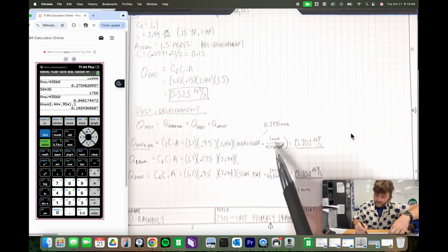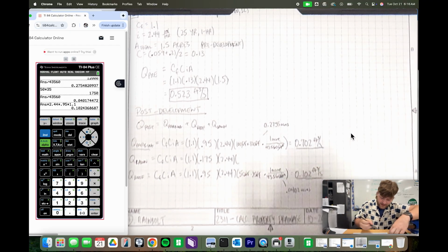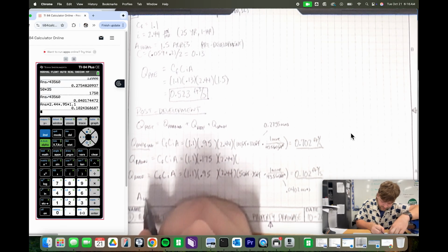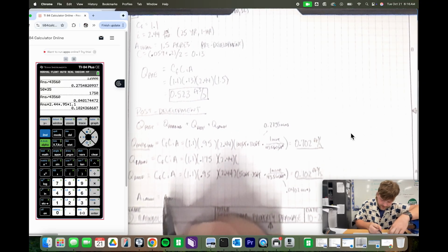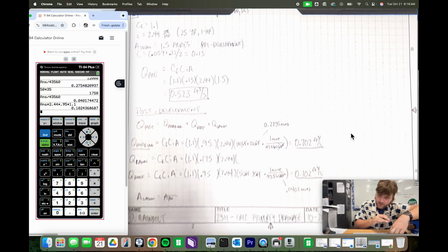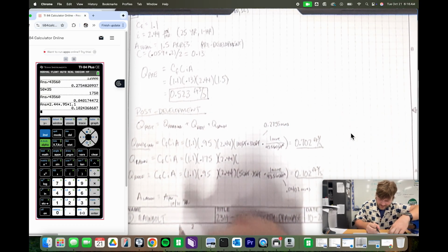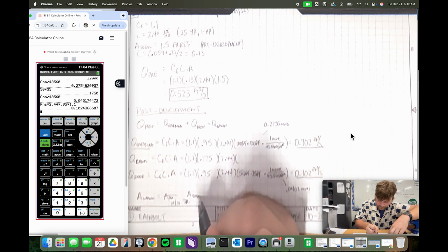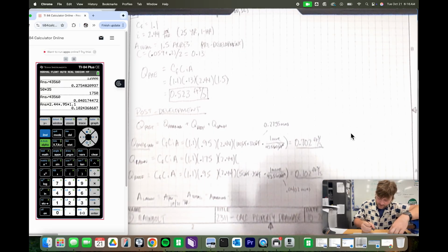Now, just as we were saying, we know the area now for the parking lot and the roof. If we take 1.5 and subtract those two areas, that remainder is going to be the area of the lawn here. So we're going to go ahead and do down here, area of the lawn equals, and we've got the area of the parking lot. Actually, sorry, let's cross that out. Remember, anytime we make a mistake, just cross it through once, put the date and then your initials. So what we're going to end up putting down here is the total area. So it's going to be a total, right, which is that 1.5 minus the area of our parking lot, minus the area of the roof, and then whatever's remaining is going to be the area of the lawn there.